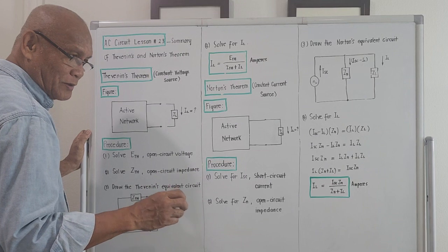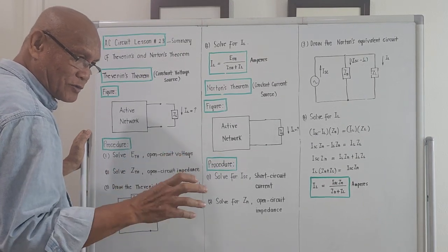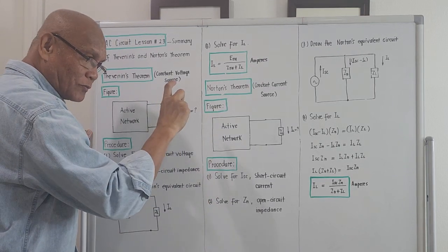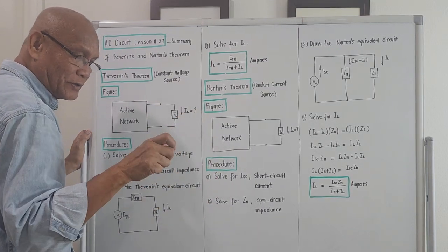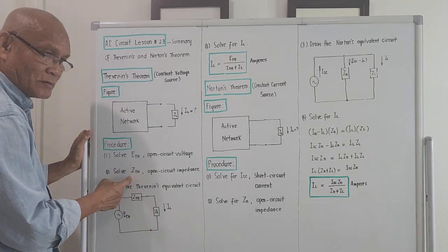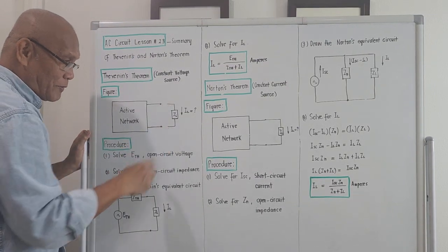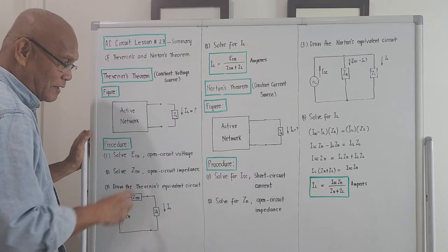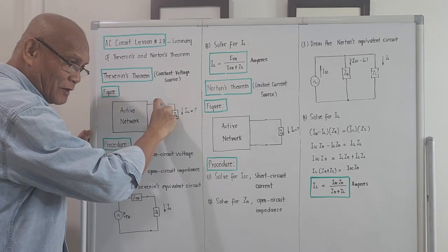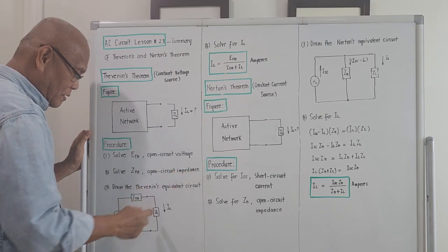It could measure the vectorial sum of a real part and imaginary part. That's why it's so-called impedance meter. You tap it here, and you could measure the magnitude of the impedance. That will be ZTH. Of course, the condition is that the circuit should be open, right? This is open. You tap your impedance meter here, what comes out will be ZTH. It is the open circuit impedance.